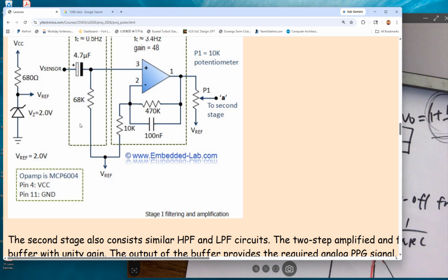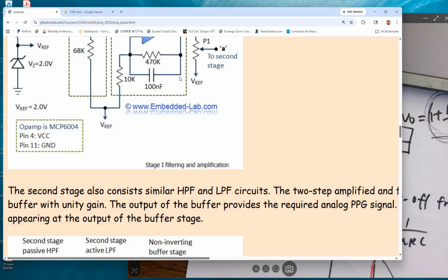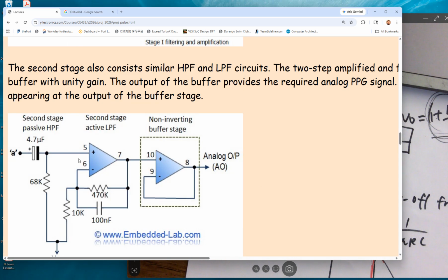But at least for this project, we learned a lot of things, right? So first, we need to remove the undesired DC bias from the sensor using a high-pass filter, and then we lift it by a desired DC bias, right? And then we run the signal through a low-pass filter and a DC gain. With a DC gain, it's an active low-pass filter, so we get a signal amplified and high-frequency noise removed. And then we need multiple stages to increase the signal-to-noise ratio.